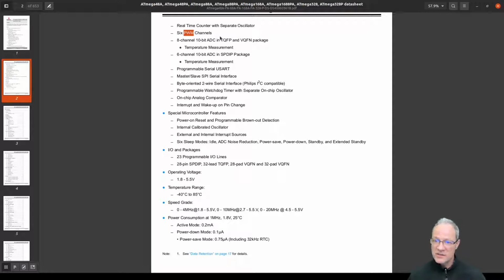Certain sensors need this PWM shaped in a certain way. For example, the dust sensor. The way a dust sensor works, it shoots a laser, and then the laser reflects from some dust particles in the air, and those reflections hit another sensor, right? So this laser pulse also has to be shaped in certain ways so that we can correlate the number of dust particles in the air to whatever the sensor is reading. Right?